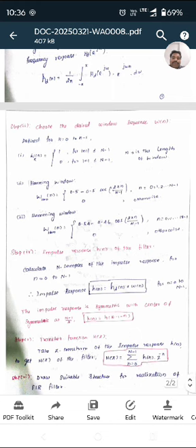Then we go for step 5, the transfer function H(z). We take the z-transform of the impulse response h(n) and get H(z) of the filter. So H(z) equal to the summation, the fundamental formula, of n equal to 0 to N-1 of h(n) z^(-n).